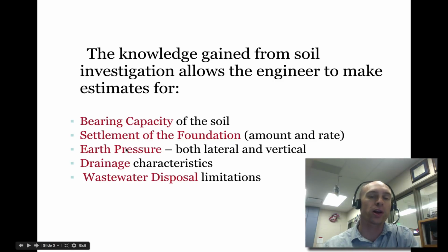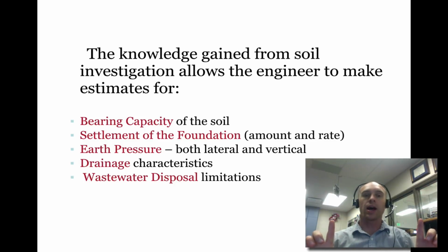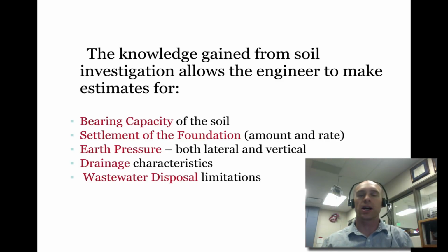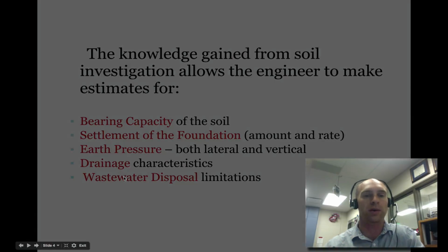The earth pressure. So, earth pressure being against the sides of the building. If you build your foundation underground, usually you would dig out, however far you need to dig out, you put your footings under the surface level. Well, then when you backfill all that dirt in, it's going to be pressing in on those walls. So soils engineers and soils investigations can give you earth pressures. Drainage characteristics, also wastewater disposal limitations, and we've talked about wastewater already a little bit.